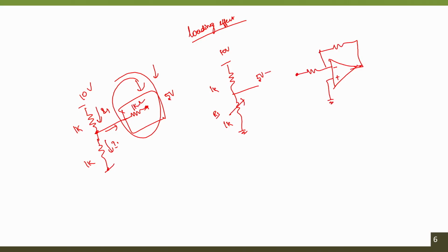the output voltage when there is an increase in the resistance will be in terms of 5 to 10 volts, imagine. Because V out is nothing but V in into Rs by Rs plus R. So, imagine this is 10, Rs is say 1.1 K, and 1.1, so 2.1 K, which is equal to 5.238 volts. So, any increase in the resistance will automatically increase your output voltage too. That we can clearly see.